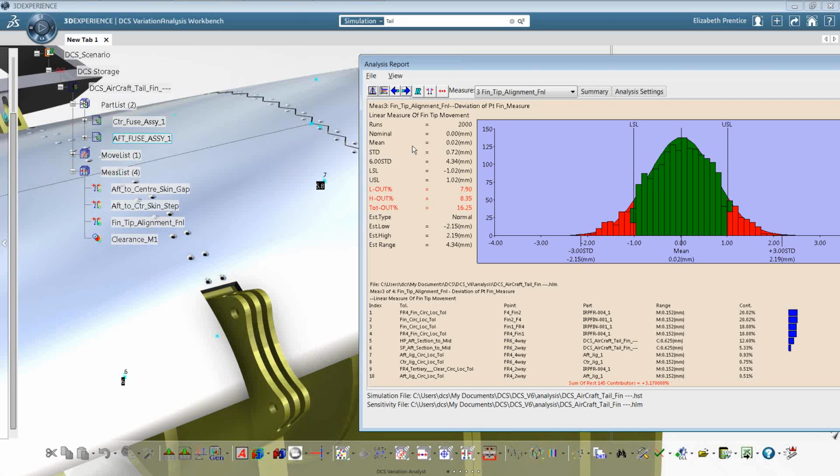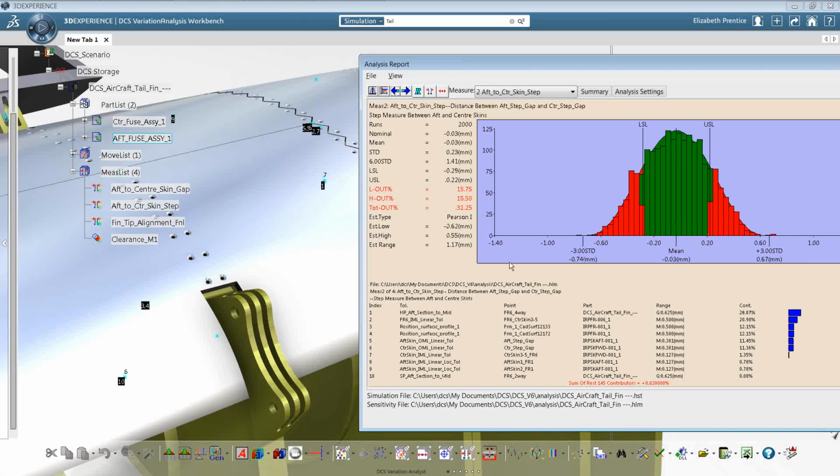Right. And then, of course, Elizabeth, this is one of the times I just want to say, okay, maybe the best answer isn't to increase the objective, but go back to that measurement. Let's say I want to just recalculate my statistics, assuming my lower spec limit went to the left a little bit. There you go. And the upper spec limit went that way. Now, we don't recommend that you solve problems just by increasing the specification, but we can get a quick idea where we need to set the spec limits and what kind of CP and CPK levels we'll have based on just quickly changing your objectives to see what's going on. Certainly we want to change the process or the tolerancing or the design, preferably, so that we can keep the same tolerance and same process.